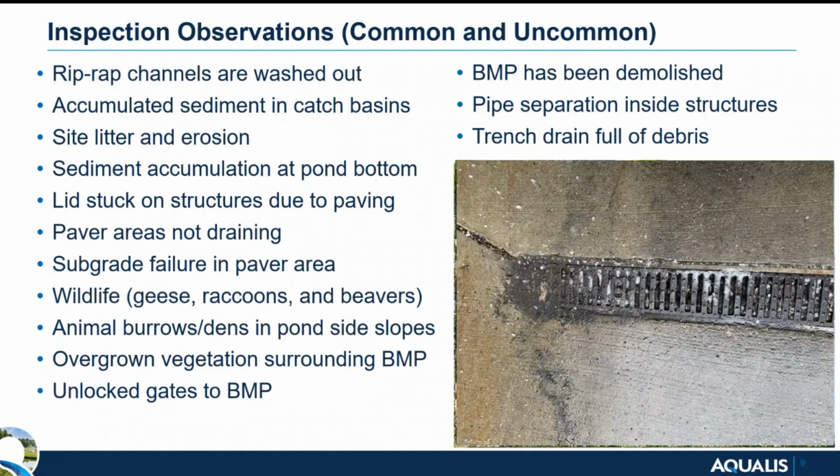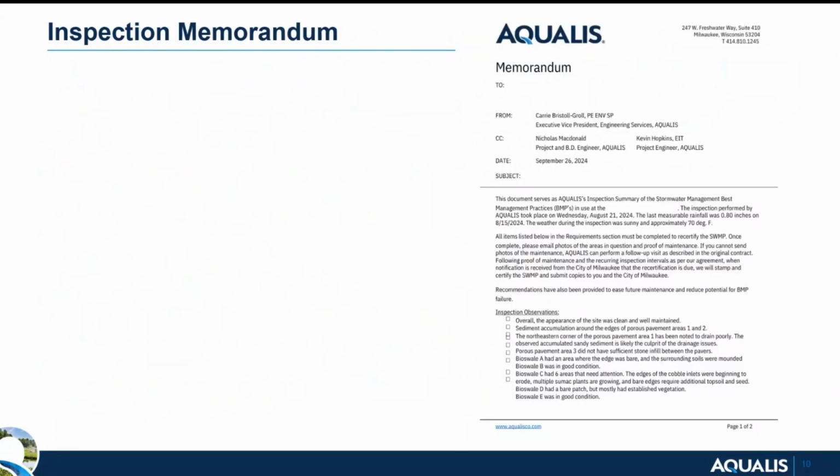And then last but not least, a lot of trench drains I've personally inspected are not clean, just caked full of mud, debris, leaves, and litter. So I just wanted to include that on our list of inspection observations.